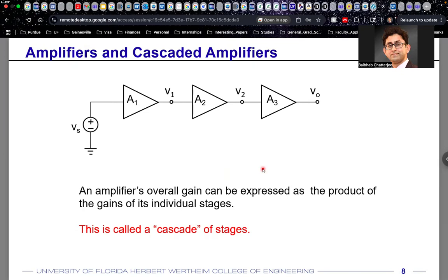The supply is supposed to be the highest voltage in the circuit, and nothing can go beyond that. And that is the reason why the voltage will be flipped. That flipped voltage will be the value of the supply. And on the bottom side as well, the value of the ground, which could be 0 volts or let's say minus 2 volts, is where it is going to get flipped on the bottom.